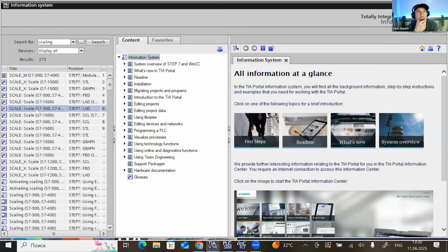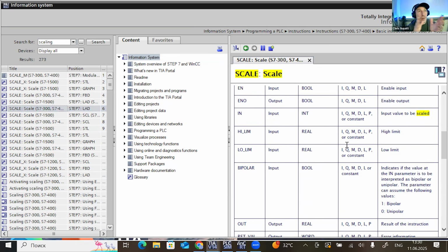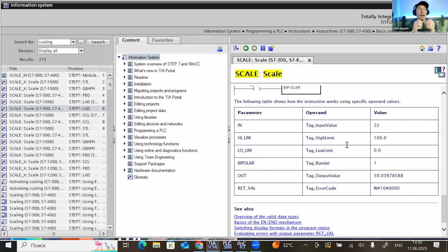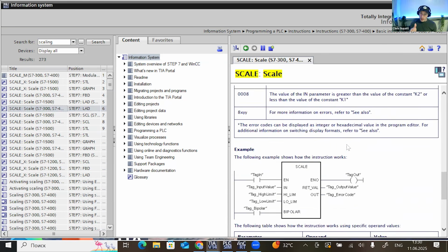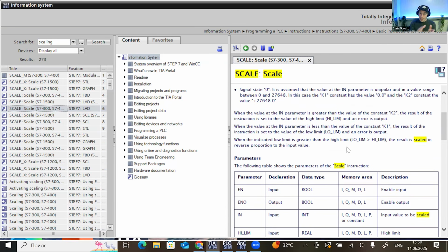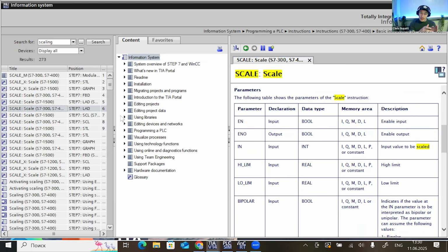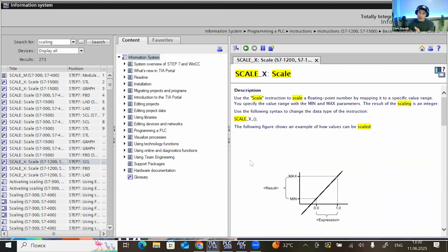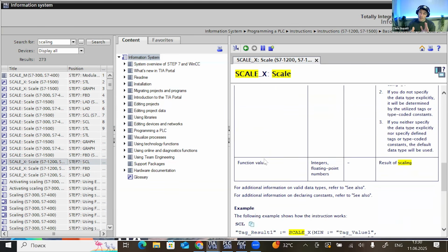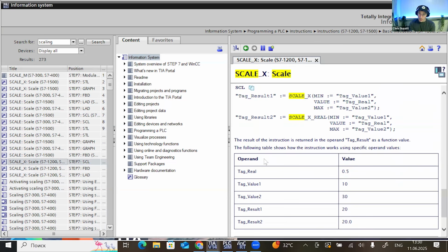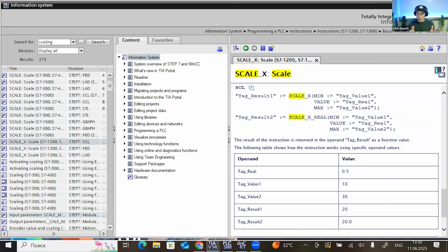Just while you're finding that, Alikhan, the half that I understood was, say the circuit is broken, like the signal cable is broken, that might read 0 the way it's set up at the moment, and you might not necessarily know whether it's a broken cable or just a low signal of like 4 milliamps. So with what you were saying, is there another reading where you can detect whether it's an open circuit?